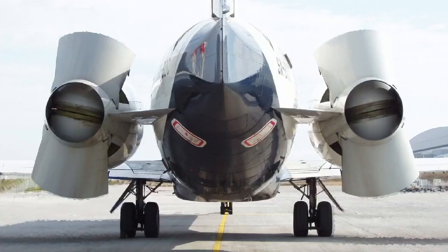During engine startup, aircraft taxi, and engine reverse thrust operation, debris can be sucked into the intake. Engine power should be kept to the minimum required to avoid damaging it.